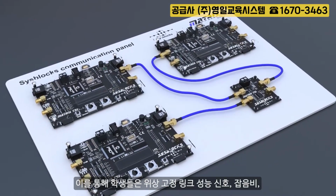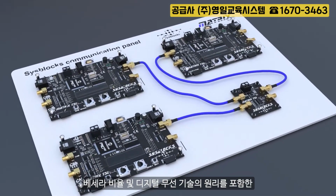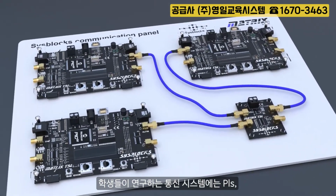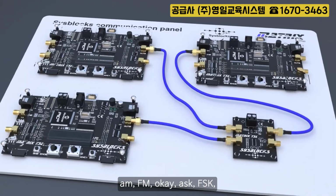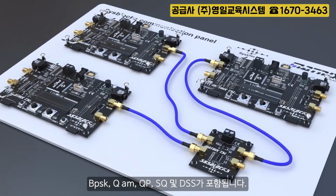In doing so, students understand the parameters of communication systems, including phase locked loop performance, signal-to-noise ratios, bit error rates, and the principles of digital radio techniques. The communication systems students investigate include PLLs, AM, FM, OOK, ASK, FSK, BPSK, QAM, QPSK, and DSSS.